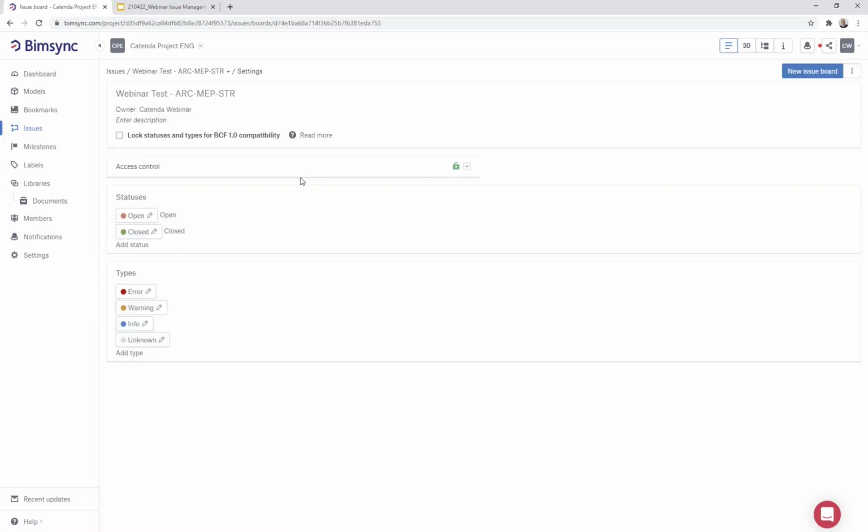So now what we have done, we have created an issue board. This will be seen when you connect to Bimsync from other software, for example, Solibri, Revit, Navisworks, and so on and so forth. You'll be able to pick this issue board and upload issues onto this.